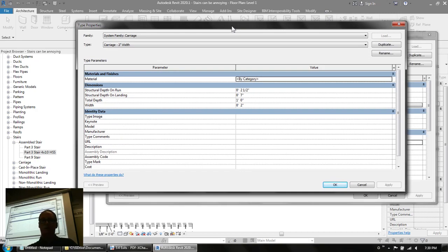On site, if you were to look at a stringer, it's probably going to be a 2x12. So the propeller heads at the Revit factory, they're right, 2x12, but they're wrong because it's actually 1.5 inches by 11.25 inches. A real 2x12 is 1.5 inches by 11.25 inches.